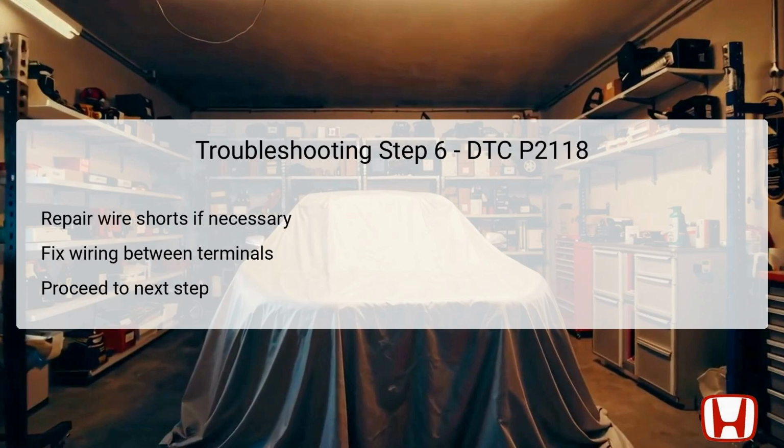If the resistance measurement in the previous step exceeds 1.0 ohm, it is important to repair any shorts in the wiring found between ECM C3 and C4, ETCSM plus and ETCSM minus lines. Here, meticulous attention is required to ensure that any breaks or shorts are thoroughly addressed, as these can severely impact throttle performance. Carefully inspect the wiring harness for any signs of damage, fraying, or loose connectors, as these can hinder